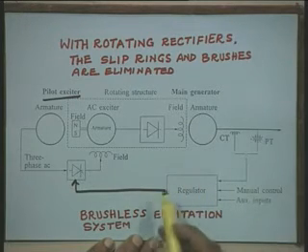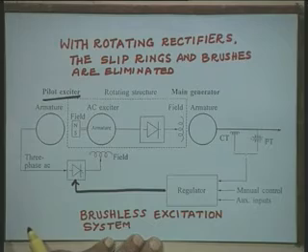The major advantage of this type of excitation system is that we do not have slip rings, and once we do not have slip rings, the problems of maintenance of the slip rings, the carbon brushes, flashovers, all these things are eliminated.